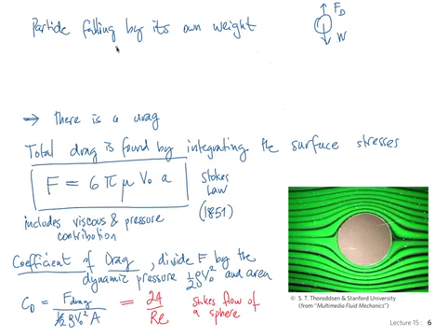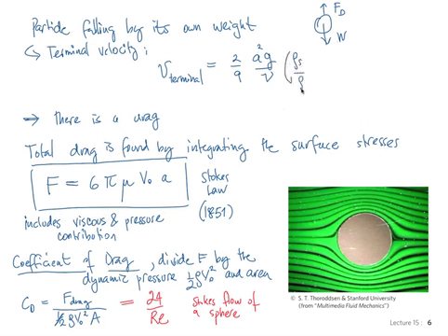And so that allows you to get a terminal velocity, or settling velocity, which is what's used, as I was explaining, in some of these applications. And the result is V, let's call it terminal, equals 2/9 a squared g over nu, times rho s over rho, where rho s is the density of the sphere and rho is the density of the fluid.